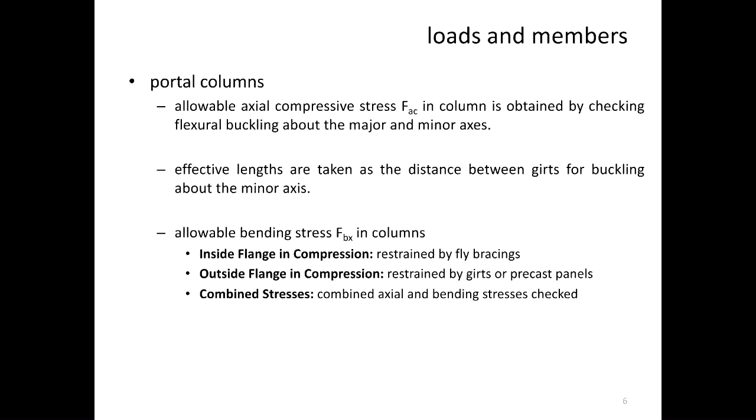How does it make sure that the structure doesn't fail before purlins and girts are installed? Because you've got the overall capacity of the rafter member, which is more than enough. Okay, so that is the strength part that is satisfied. For serviceability, you have to check all those local bucklings and make sure that they don't fail, which is why we have certain other elements which I'll talk about shortly.